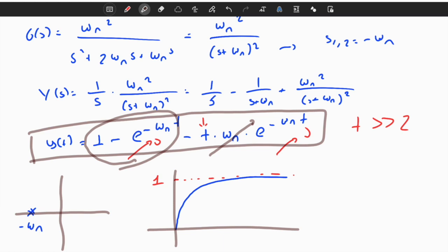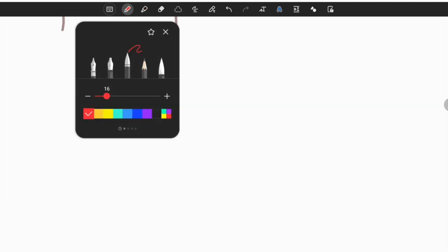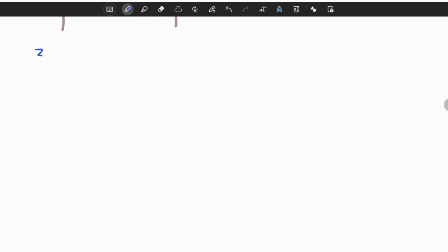As you can see, it is equal to 1. That's nice. Now we will move on to more general, or let's say more probable cases, because psi equal to 0 was undamped, and psi equal to 1 is critical damp. These are specific cases, and this happens only when psi is equal to a specific value. Now let's analyze the case when psi, let's change the color, zeta or psi, is greater than 1.